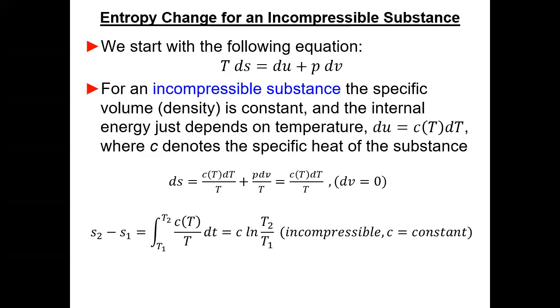Okay, now we're going to have special situations. We've got ideal gas coming. We've got incompressible substance. If you're working with water and you want to assume it's incompressible, nothing is totally incompressible, but the amount of the error involved in liquids and stuff like that is usually pretty small. So for most processes, it's okay for a liquid or a solid to assume it's incompressible.